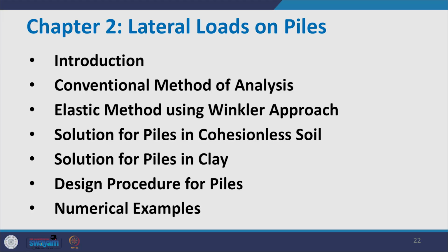So, continuing with the last lecture, in which we discussed lateral load on piles. In the last lecture we talked about the introduction, then the conventional method of analysis, and the elastic method using the Winkler approach. Now we are going to apply whatever we have discussed in the elastic method using the Winkler approach. If you recall, in that method we defined a coefficient called the coefficient of modulus of subgrade reaction, eta h.